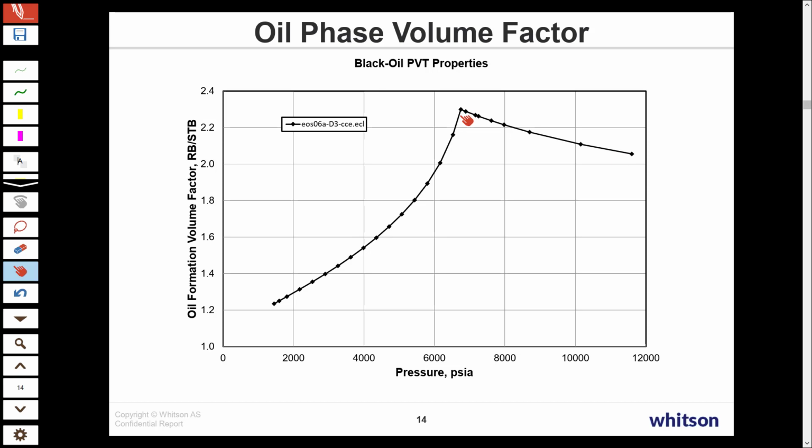But when we go below the bubble point, the change in oil volume is more abrupt, and it's caused mainly, well, exclusively, the reduction in volume is coming directly from the fact that gas is coming out of solution. It's losing mass. So the oil is shrinking because gas is coming out of solution. As more and more gas comes out of solution, the oil volume shrinks down towards approximately 1, if you forget the temperature effect down below.